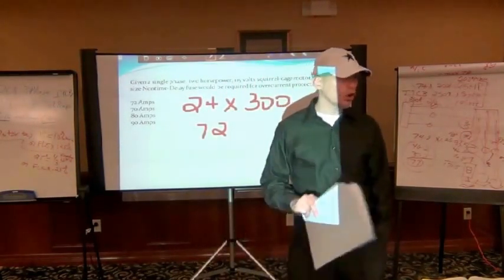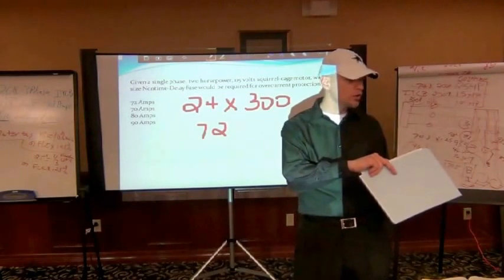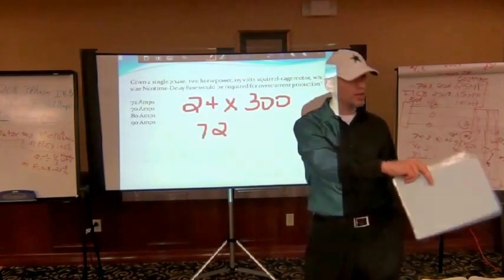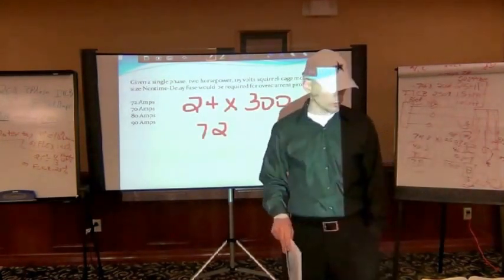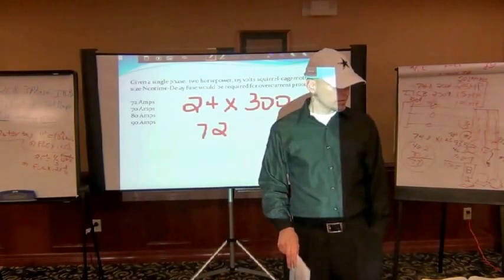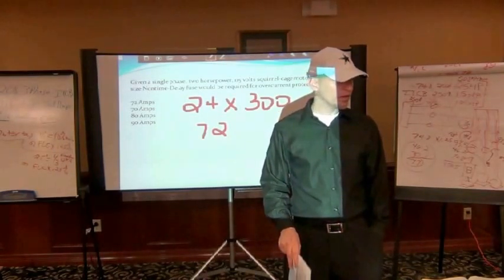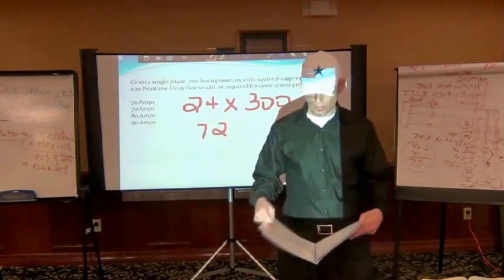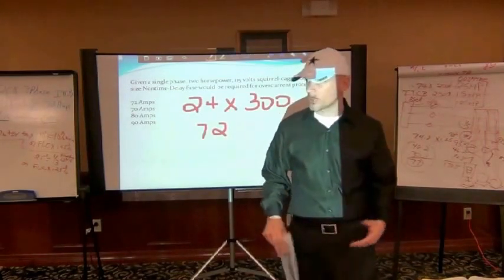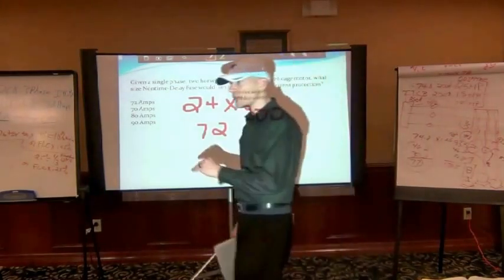Because the largest motor is other than continuous duty, you're going to use the table value, and then the sum of all other motors. What was the short time rating now? It was a 15-minute rated motor, so short time duty 15-minute rated, so it'd be 120%, right? Instead of 125%.